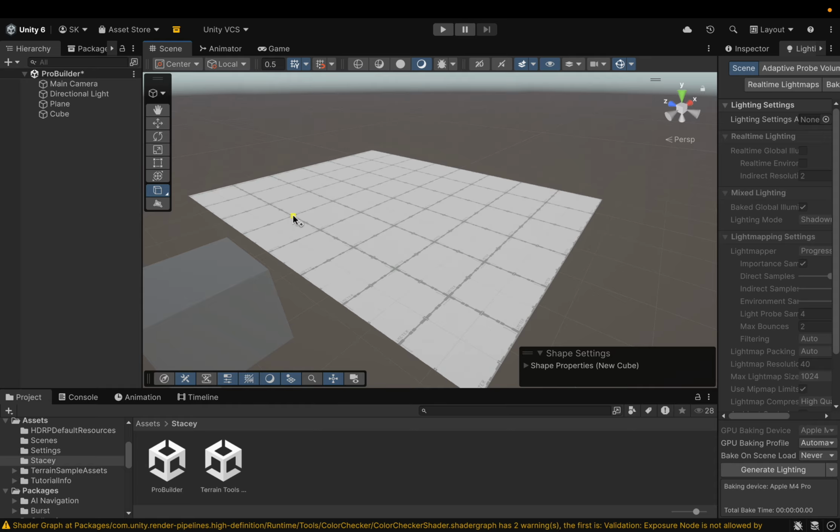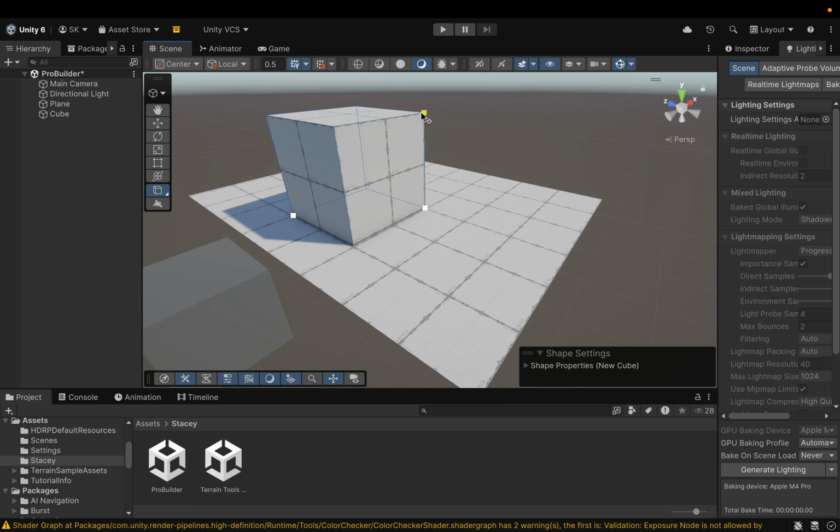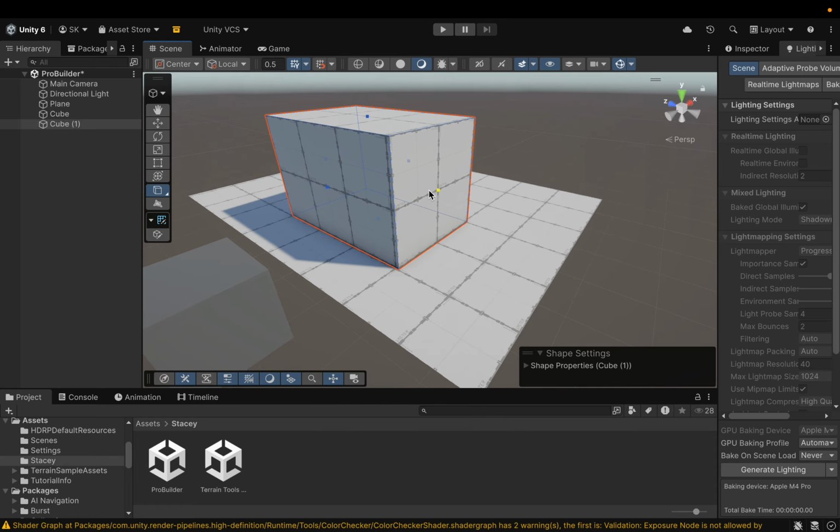So I'm going to start by dragging and creating a 2x2 cube. I'm going to click and drag to this other corner here. And when I let go of my left mouse button and I push up, it'll automatically create a height. And then if I click again on my left mouse button, it will complete my cube. And again, you can see just like the plane, I have these extendable handles that I can adjust it with.